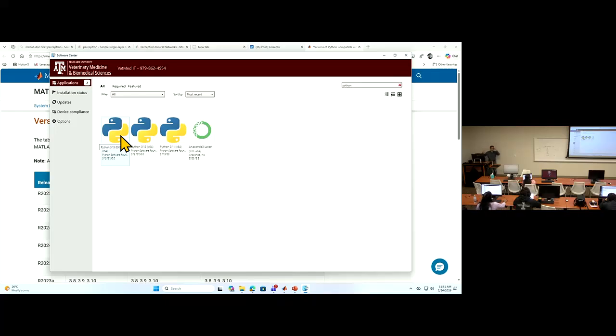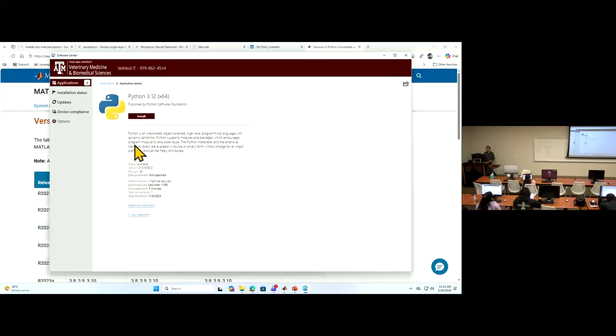The older version we are using cannot communicate with the new one, so we need to install this slightly older version. Once we have this done, we should be able to find where our Python executable command is installed. Then we link that command line into MATLAB, and we set it up.